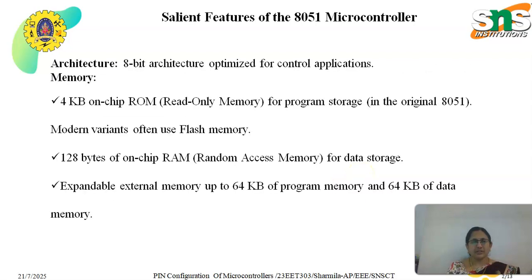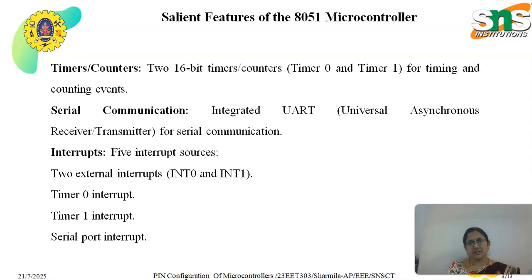And the next one is the timer and counter part of the 8051 microcontroller. In this, two 16-bit timers and counters are available, named timer 0 and timer 1, for timing and counting events. And serial communication is also used in the 8051, that is UART, which is nothing but universal asynchronous receiver transmitter, for serial communication.